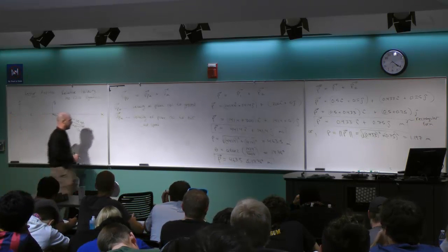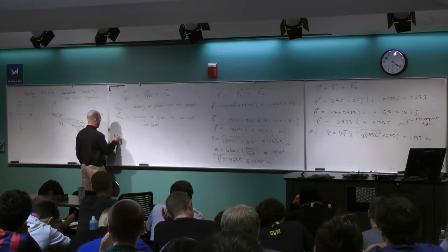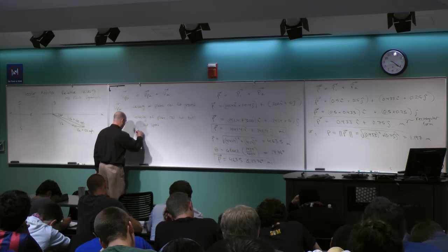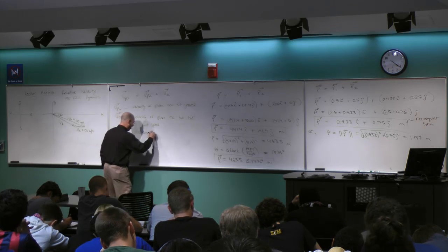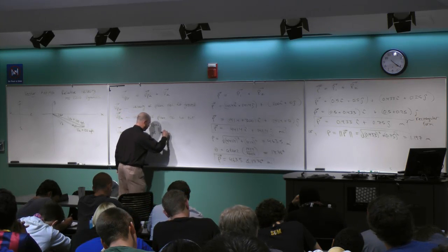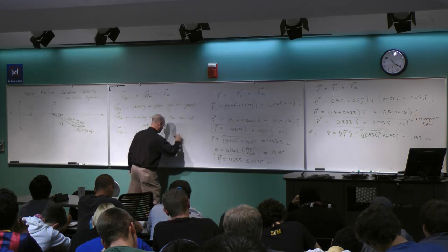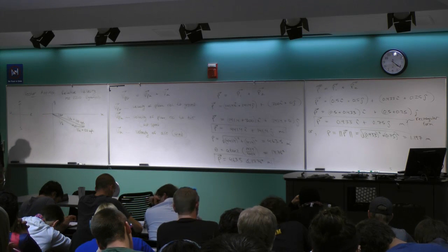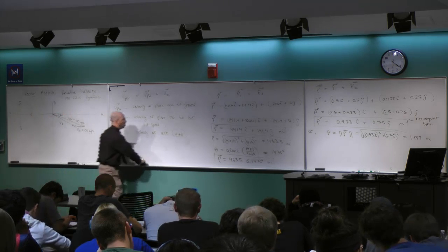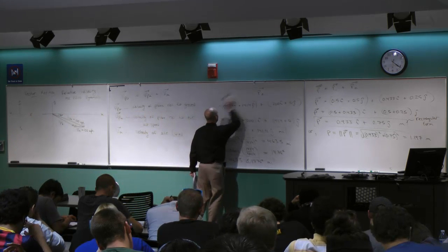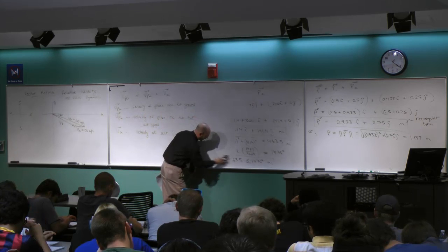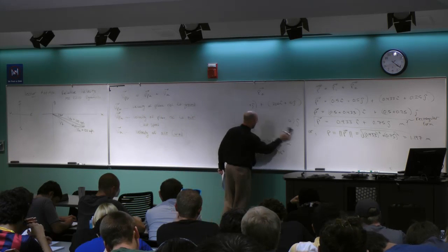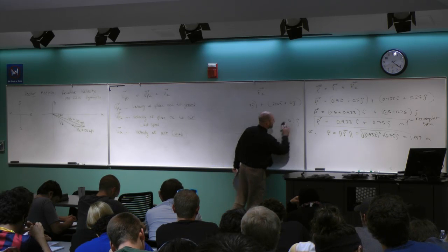Okay, and then finally the VA there, that's the velocity of the air itself, which is really the wind speed. Okay, so velocity of the air itself, which again, the wind. That's what we're taking into account. So that's the principle. If I want to find the VPG, again, it's the same skill set. I want to write down each of these things in vector notation, and then add them up.